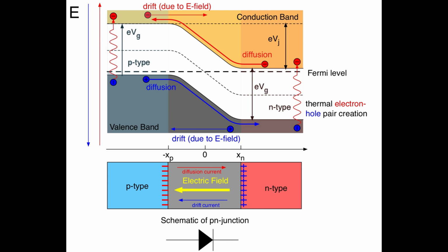The depletion region in a silicon diode is a region near the p-n junction where free charge carriers, electrons and holes, are depleted, leaving behind immobile ions. This creates an electric field that acts as a barrier to current flow. When forward biased, the applied voltage reduces the width of this barrier, allowing current to flow. When reverse biased, the barrier widens, preventing current flow, thus the switch. As you can see, the depletion region between the two with no battery applied.